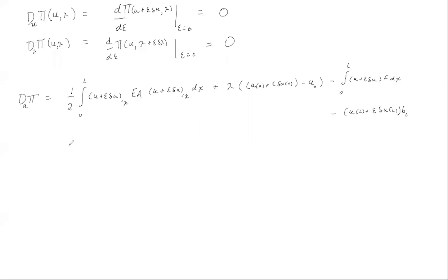All right, so what we're going to do is take this entire statement, differentiate it with respect to epsilon, and then set epsilon equal to 0. Oops, it's the edge of my pad, sorry. All right, so let's do the derivative first. The integral, we're assuming that it does not depend on the displacement because of our small displacement assumption. So this differential operator can pass right in through the integrals.